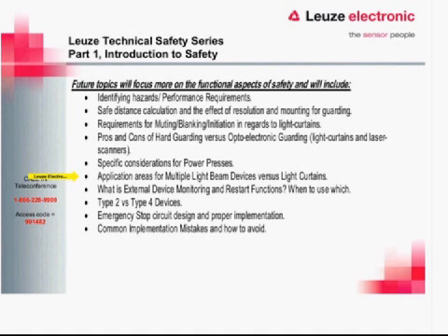We'll look at different application areas for light beams versus light curtains. What is an instance where a light curtain would work? When would a multiple beam work? Sometimes there are instances where both will work, and we'll go through that and help you figure out what is the best thing you're going to need for that type of hazard. EDM and restart functions, we'll go through how those work, why we need them, and how to use them correctly.